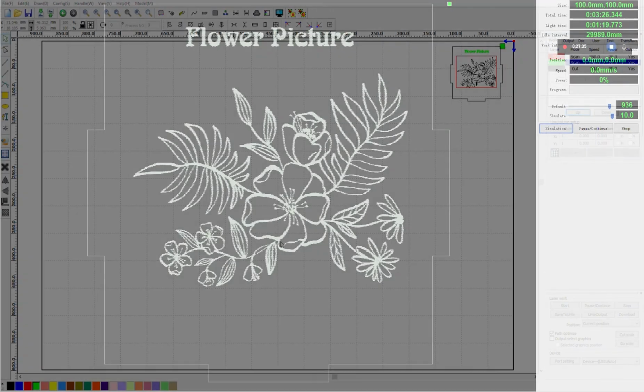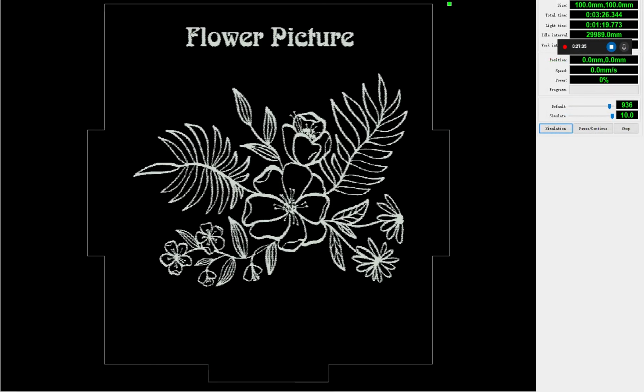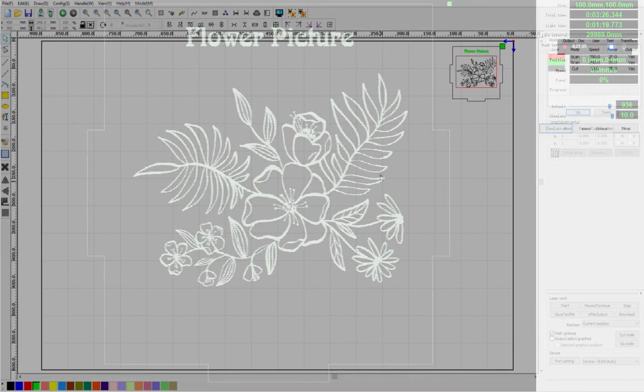Once you are satisfied, use the preview tool to run a simulation or at least find out how long the job will take. You can also toggle on the show path control to see if things could be positioned more efficiently in terms of laser head movements when it's not cutting or engraving. Efficiency is not super important in the Science Maker Lab other than minimizing wastage of wood. However, if we're going to do a production run, careful placement and setting up files to share cut lines wherever possible can save significant amounts of laser time, leading to much lower production costs. Once we're set on our layout, we can close the preview and we're ready to export.